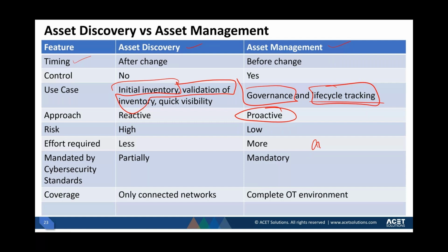So a lot of these end clients also feel reluctant about allowing third-party tools on the network. Generally, passive discovery is more accepted by end clients, and even by some of these DCS vendors. They have started opening up to passive discovery tools as well.